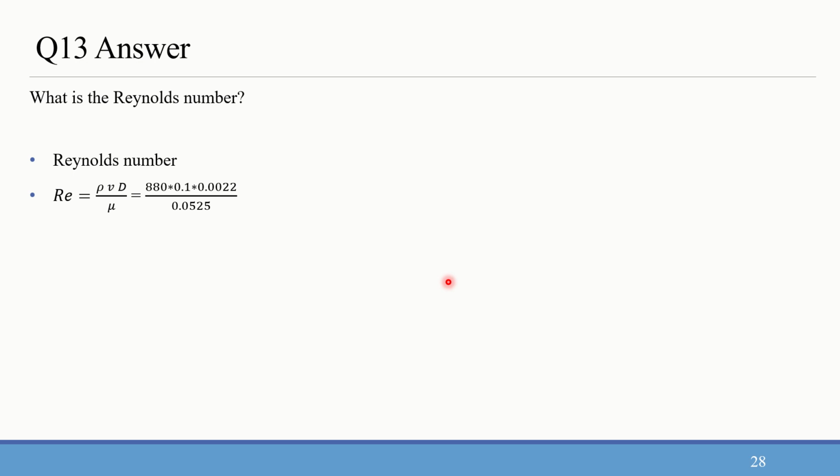If velocity is 0.05, what happens is 3.69 divided by 4. Even then it would be 0.92. But it is less than 1. So when velocity is half or less than half, in this particular condition, we can use this particular setup to measure the viscosity of the fluid.